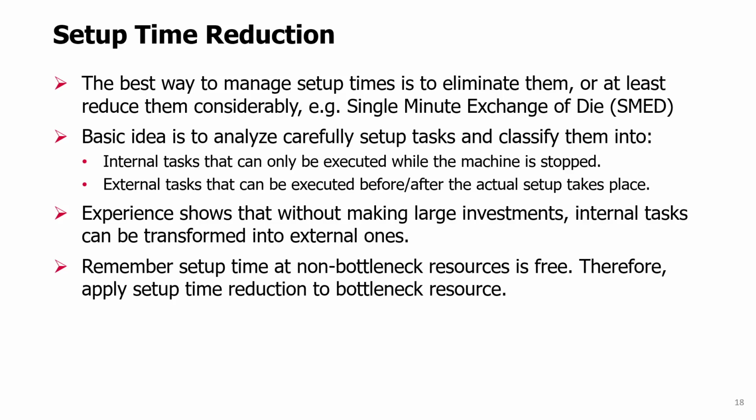And a final comment about setup time reduction is that setup time on non-bottleneck resources is really not important. If you have a resource which has a lot of capacity, even when you produce things with very small batches, and this is still not a bottleneck, then it doesn't make sense to try and reduce the setup time on this resource. Only when the resource at small batch sizes is becoming a bottleneck does it make sense to work on setup time reduction, because this is what will lead to improvement in capacity when batch size is very small.